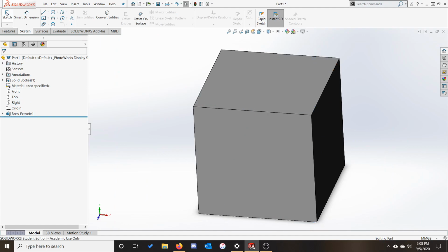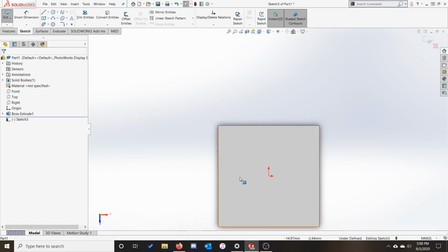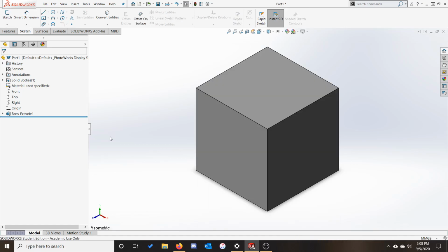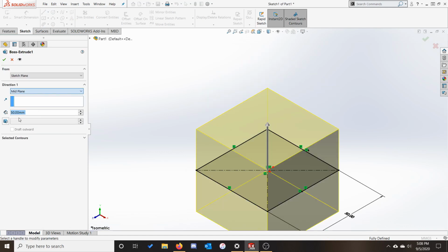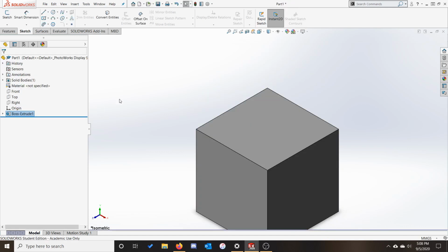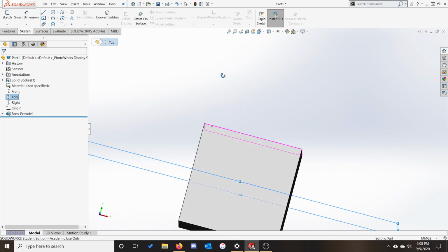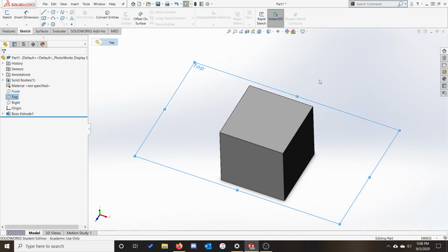In addition to this, if we were to open a sketch on the top or bottom surface of the cube, we can see that the origin is now centered instead of being in the corner. Let's do one better. By modifying our extrude's end condition to change it from blind to midplane, we freed up the top plane as well, giving us a total of 9 unique surfaces that we can use for sketching, for starting and ending conditions, or for other future tools.